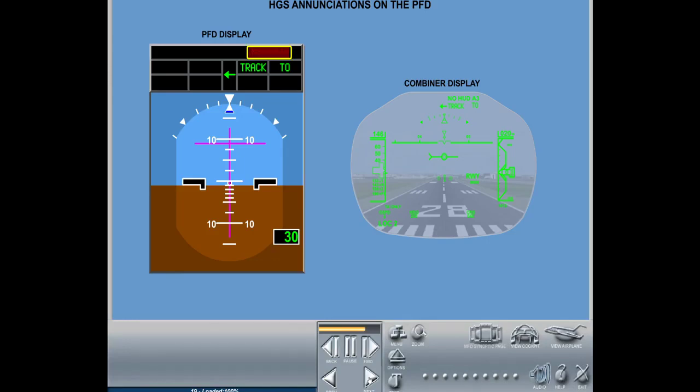During A3 approach operations and when the aircraft is below 500 feet ASL, the annunciation No HUD A3, red letters, shows on PFD to indicate that the HUD A3 guidance function is no longer available due to system or sensor failures or data miscompares.